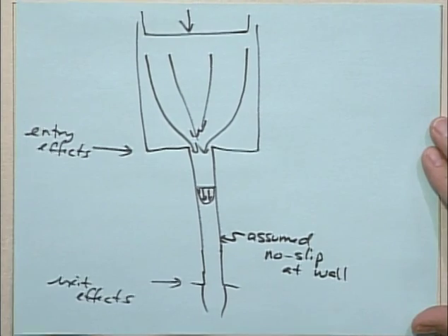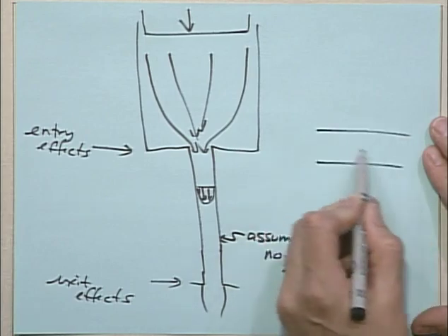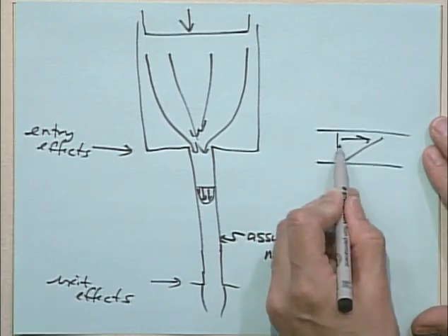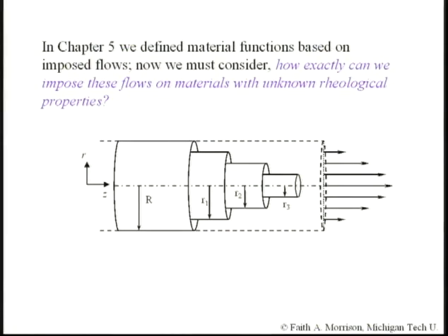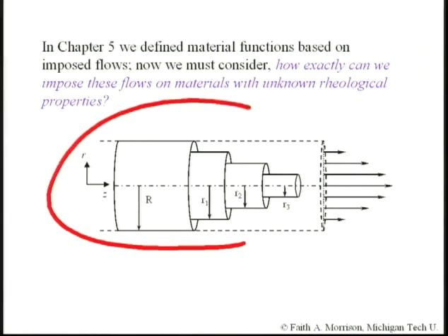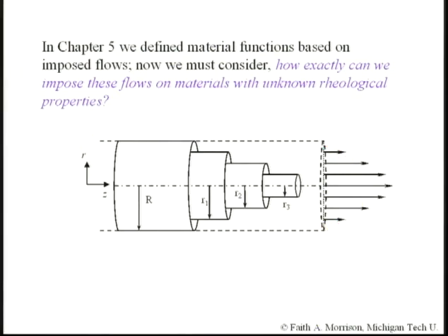And maybe the big picture, the first thing I should really talk about is why flow in a tube would be a good analysis for shear flow, when in fact it's not shear flow, it's this parabolic velocity profile in a tube. So addressing that issue first, if I go back a couple of slides, this is what's happening inside the capillary tube itself. There are layers of fluid telescoping one inside the other.